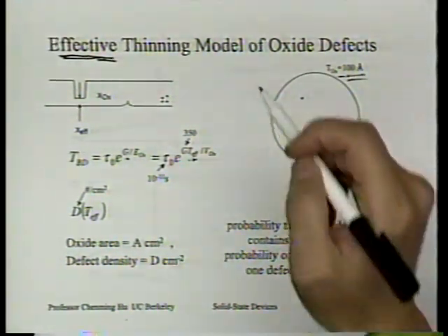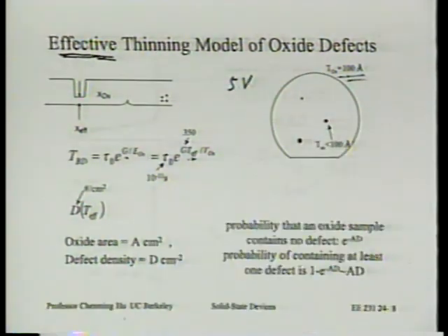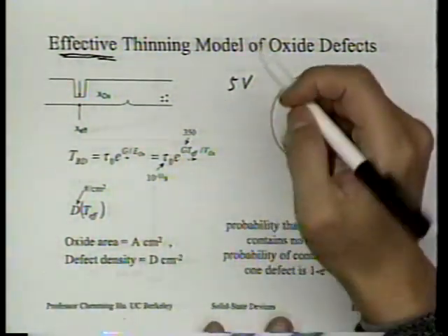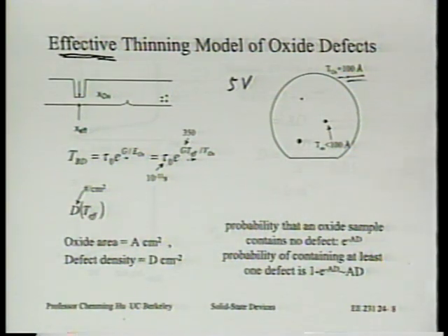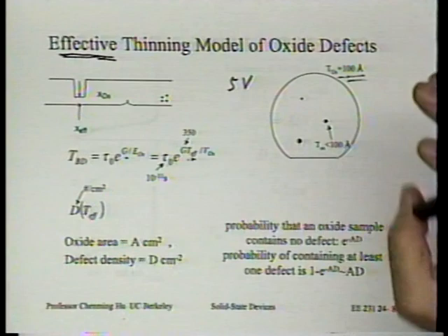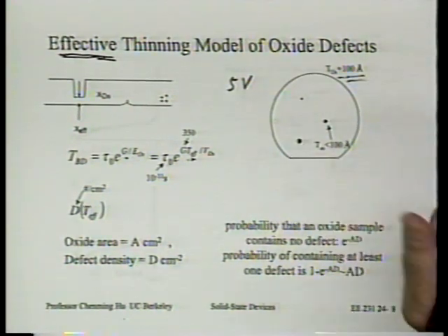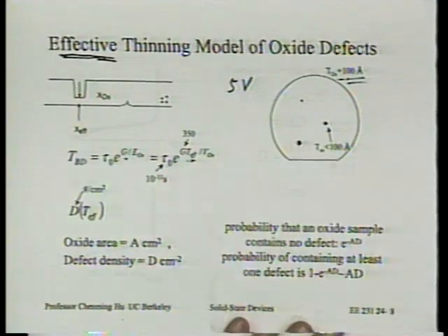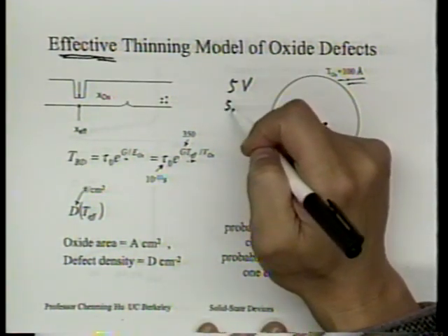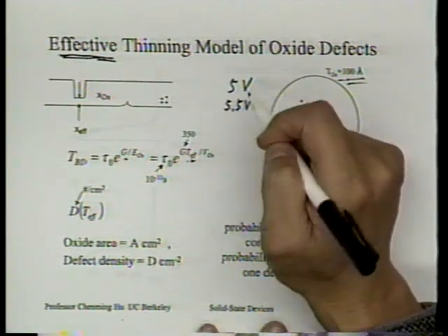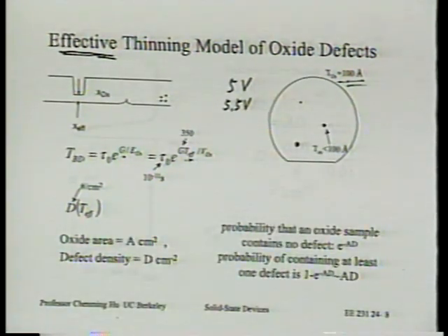All right. We're using this as a 5 volt. In fact, we'll call this 5 volt VDD, using a 5 volt product, suppose, all right? You can see this is very aggressive to try to do that, all right? 5 volt product, okay? In fact, if it's just a 5 volt product, we probably should assume we need 5.5 volt as the maximum possible voltage, because typically the manufacturer of the product will say, we tolerate plus minus 10% of VDD, all right?